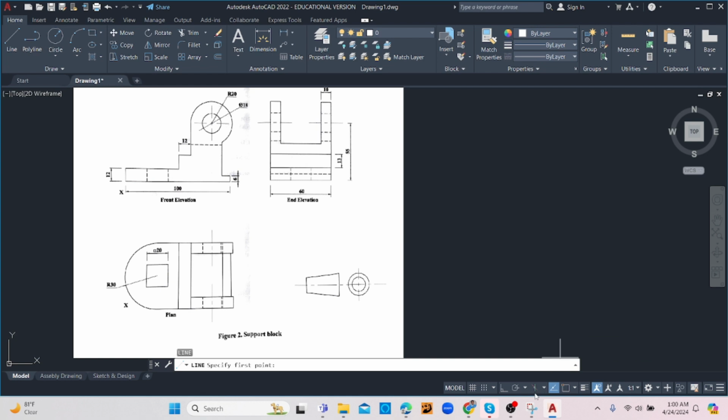Let me first turn on my ISO mode, and I'm going to stay on ISO right-left for now. I'm going to simply be drawing a rectangle just to put things into context, and I encourage turning on ortho as well. I'm going to be drawing a rectangle, with the width equal to the width of the object itself. In this case it is 60.